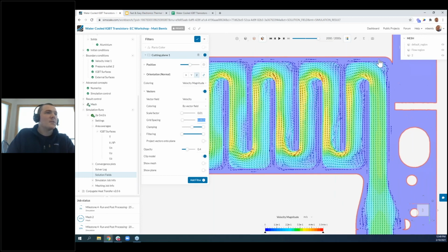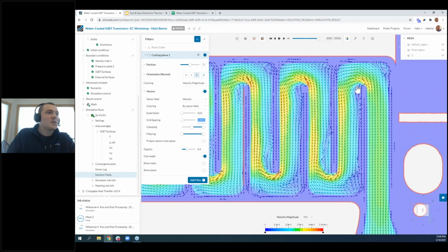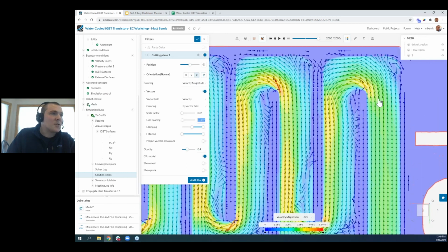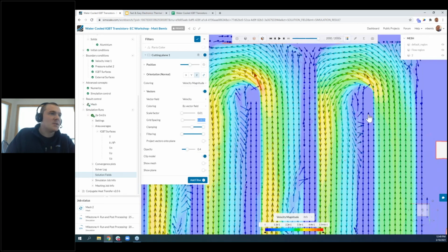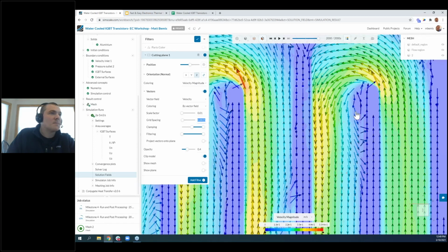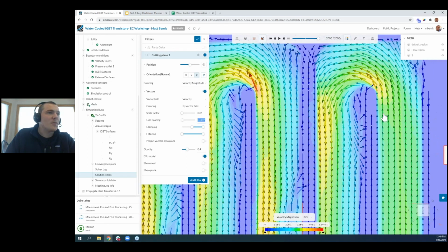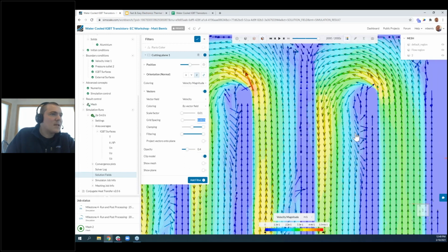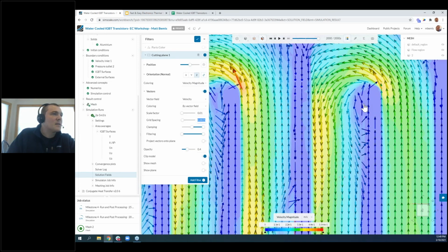Here we can start to understand how the flow goes around certain sections and changes direction. What I'm interested in here particularly is we may have some recirculation zones. What's that mean? Well, we actually have flow going in the opposite direction of the dominant flow direction. We see a peak here. Of course, the flow actually speeds up as it bangs in that corner, is forced to accelerate and go down the screen. And we see some vectors sort of getting stuck, and we have low velocity here.